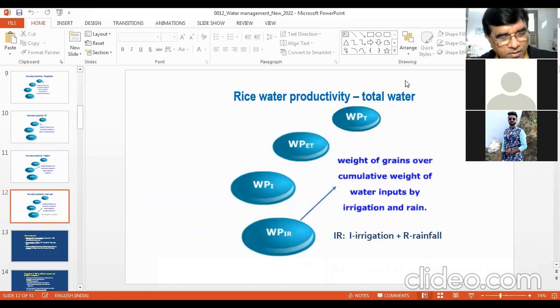And this water can be water that is used in irrigation, water that is coming by rainfall to the field. It can be reported in different units. Number 1 unit is hectare centimeter. Hectare centimeter means you have 1 hectare area. In that 1 hectare area, the height of the water is 1 centimeter. So then you convert this 1 centimeter to meter. 1 divided by 100, it will be 0.01. This 0.01 can be multiplied by 10,000 because that is the area of 1 hectare. And whatever you get, that is the cubic meter water in 1 hectare.